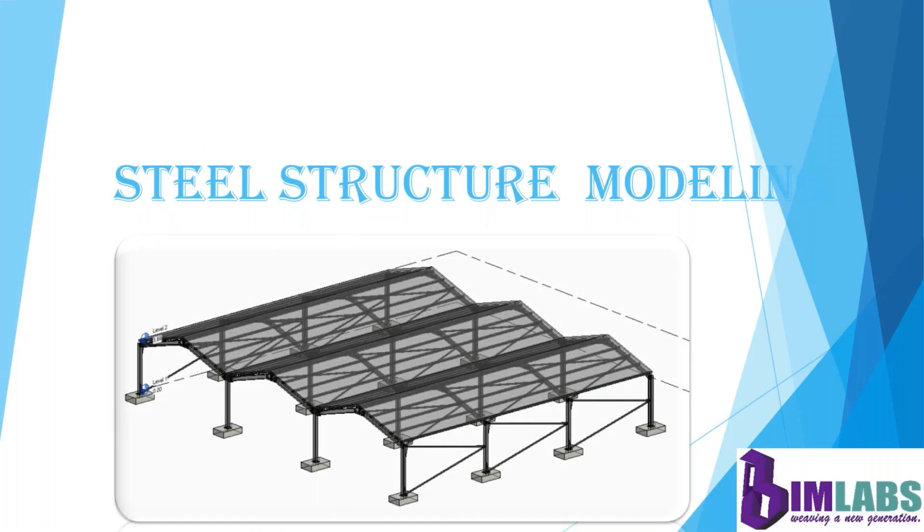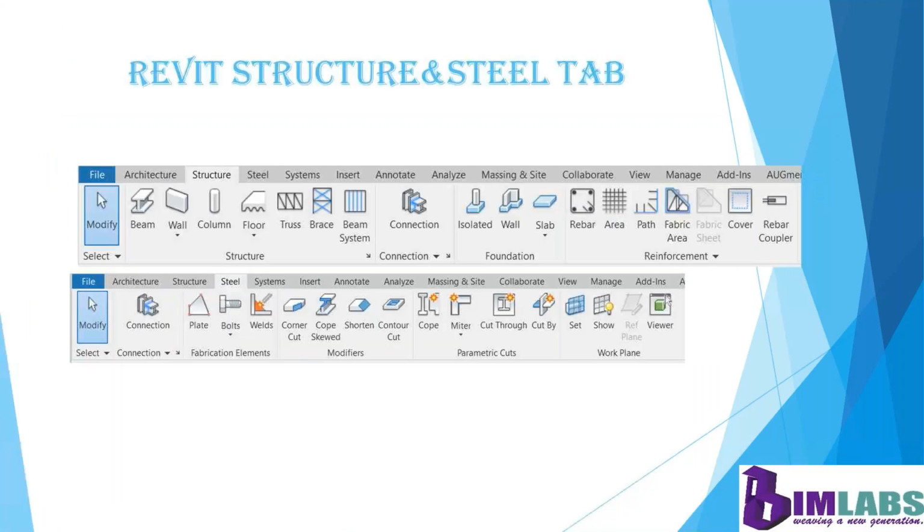Then comes your steel structure modeling. Till now we were discussing mostly concrete structures. In concrete structures, in the Structure tab, you will have beam, column, wall and everything, and rebar is also available in the Structure tab itself. In the same way, you have the Steel tab. In the Steel tab, we have different types of connections and different types of fabrication elements like plate, bolts, welds and everything.